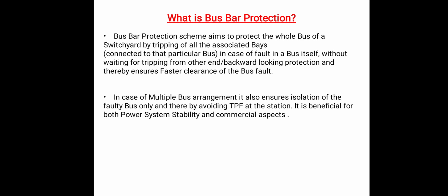Busbar protection needs some special type of attention because of some different reasons. The fault level at busbars is very high. The fault on the busbar would result in wide supply interruption. The system stability is adversely affected by a fault in the bus zone, and in the event of a fault on any section of the busbar, all the circuit equipment connected to that section must be tripped out to give complete isolation in the shortest possible time.